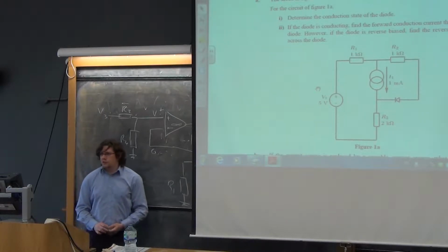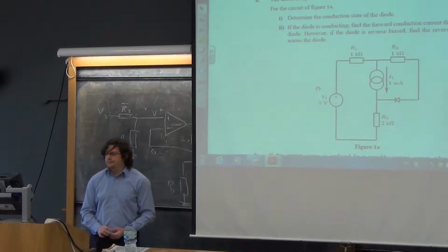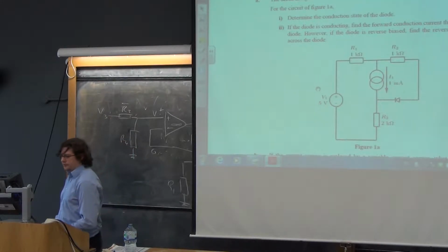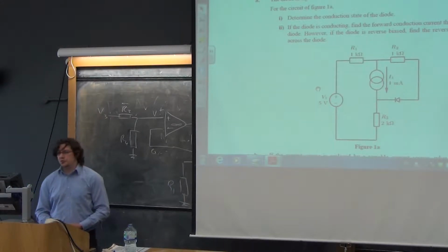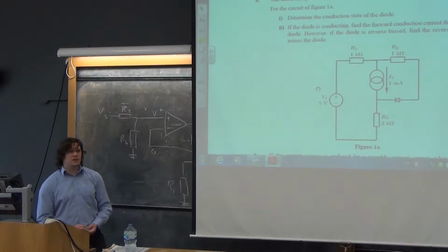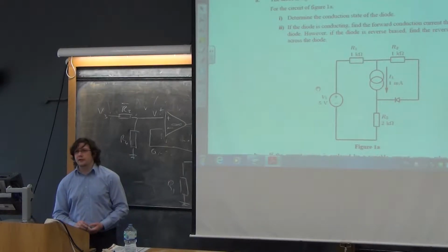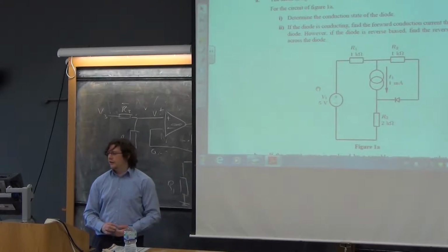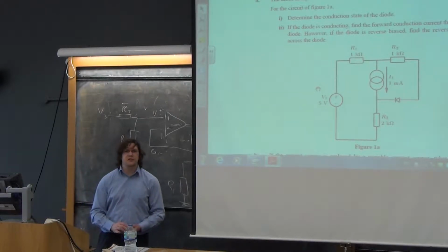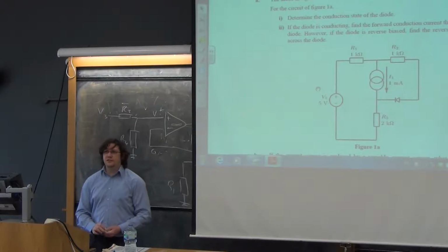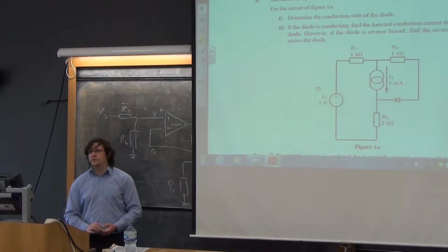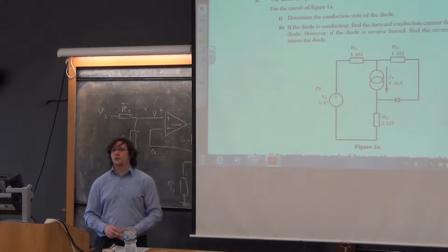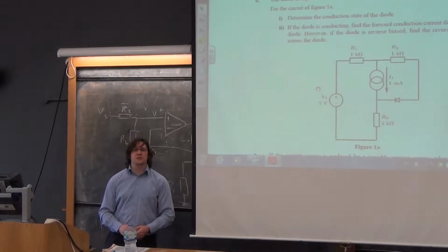So this was the diode question. And there's a circuit with 3 resistors, 2 sources and a diode. And this is the usual sort of strength question. Actually, this question's got a secret trick in it, where you can collect 2 of the resistors together. If you've been reading your circuit theory, you'll know that R1 and R3 can be collected up, because you can move R3 to the other side of V1 without actually changing the mathematics of the circuit.